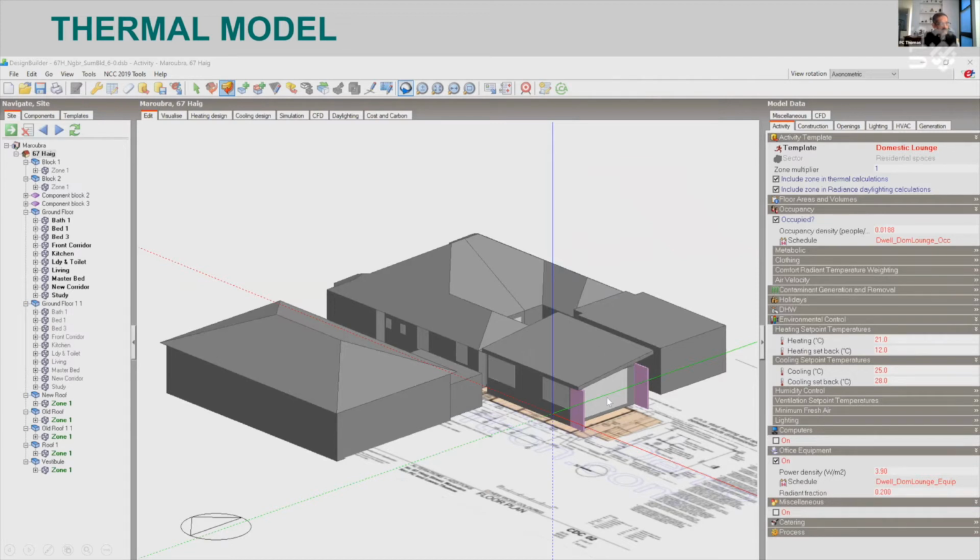They're not really modeled as a thermal performance part of the building. Now, these models were built almost 5 years ago. If I was rebuilding these models, they would be different. This would no longer be a whole model. It'll probably come out in pink because all I need is its shading impact on my building. The one that's the semi next to mine, I would have built that as an adiabatic model because I don't really want to know much about the heat transfer between them since that part is kind of insulated from the other.